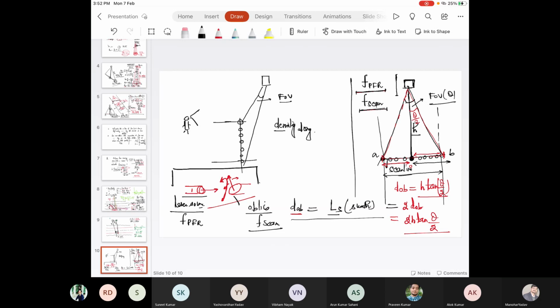So density along is equal to the total number of points, capital N, divided by swath W. And what is the length of the scan line? We have calculated 2H tan theta by 2.